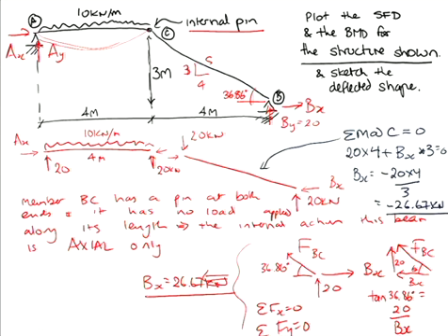So I have a minus sign this side this time because my arrow is going in the opposite direction. I should have really put it, well, I left the minus sign out here because I was working on that basis and I'd already rotated it round. So the important thing to note here is just that you recognise member BC is effectively like a truss member, it only carries axial load. Okay, so knowing that, deflected shape.